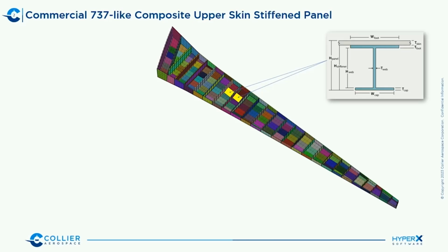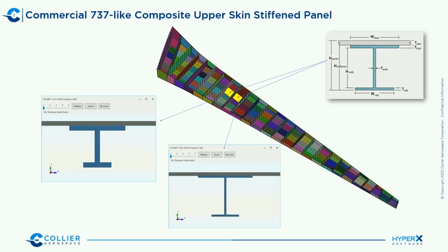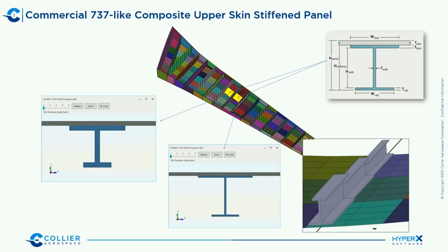even though we have an I-shaped stiffened panel on either side of that rib, they're like neighbors, right? The way that the software would optimize potentially is to come up with a compact section on the left, as you see there, and even though it may have the relative same area, the same kind of mass, it's a vastly different design. It's slender, right? It's taller. And the issue with that is manufacturing.